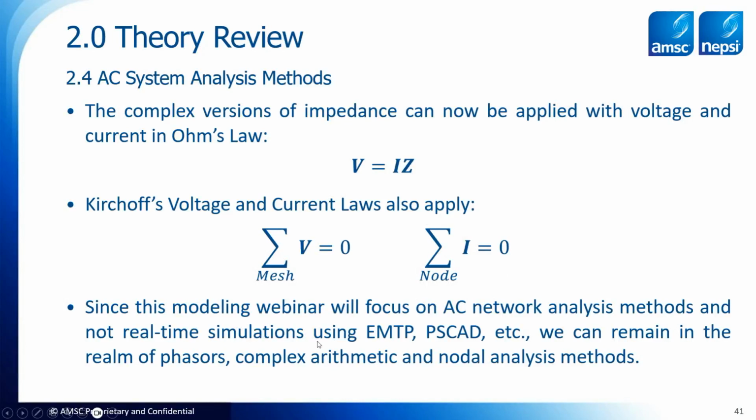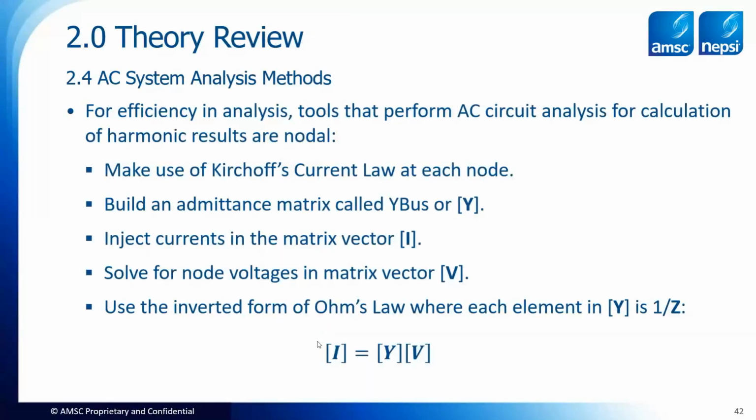Now, since this modeling webinar is going to focus on AC network analysis methods and not real-time simulations like with EMTP or PSCAD, then we can remain in the realm of phasors, complex arithmetic, and nodal analysis methods. For efficiency, so that we can perform these calculations as quickly as possible, a lot of things were discovered. Obviously, making use of Kirchhoff's current law helps us to perform a nodal method.